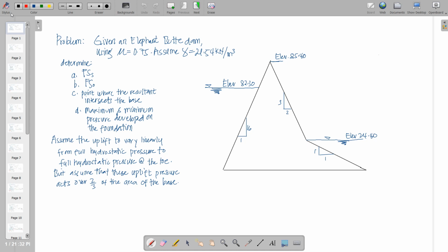So first things first, we need to divide our dam into corresponding composite areas to compute the volume. In here, the assumption is we're going to get a 1 meter strip out of this dam. So we have subdivided the dam into 4 composite areas. And then we are going to determine the base dimensions of the dam.